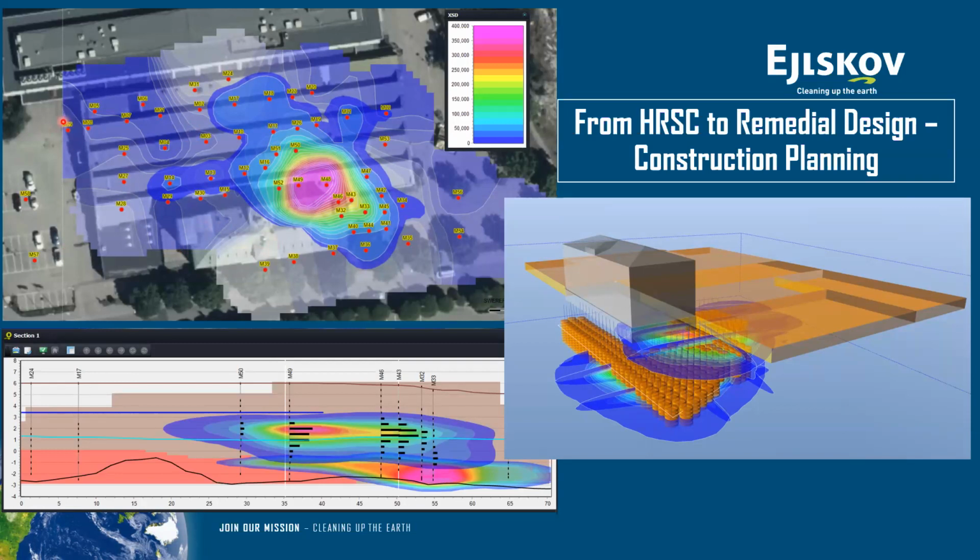And here, as you can see, the RDC was focused on truly following a specific grid with the MIP and making sure that we had covered as much of the property as possible and ensure that the client was sure regarding the presence of contamination. In this case, we identified the source in an area where previously no data showed